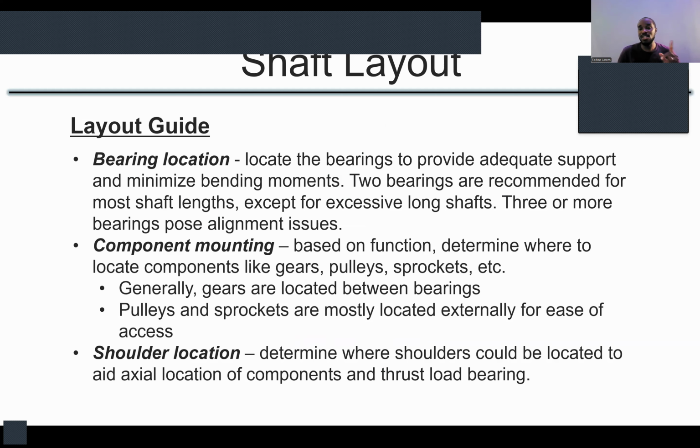Remember, your shaft is a rotating member. So if you want to support your shaft and you hold it, by holding it, you might prevent it from rotating. So bearings have been designed to support the shaft rigidly as it's rotating, so that it is not moving here and there, but also to allow it to rotate freely.